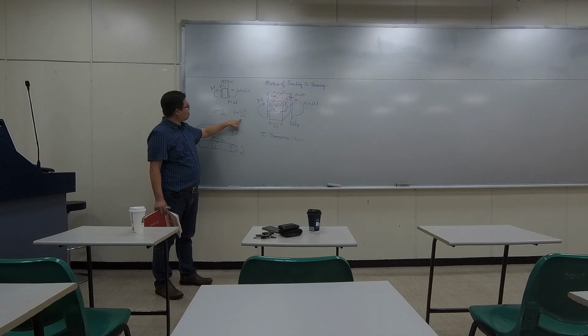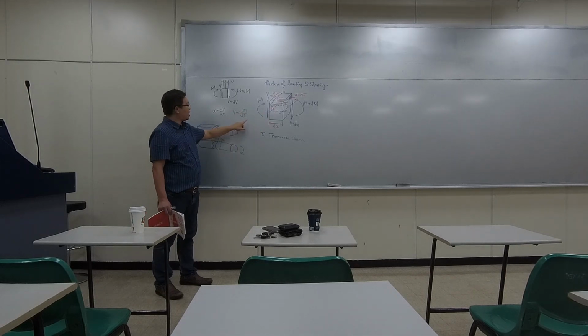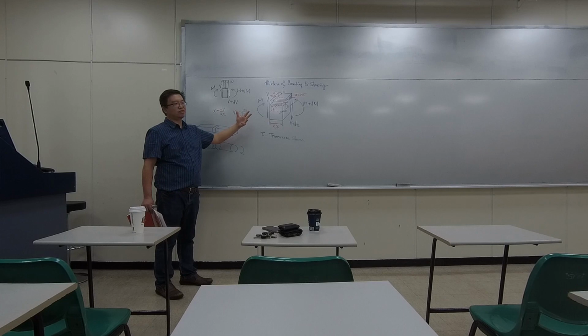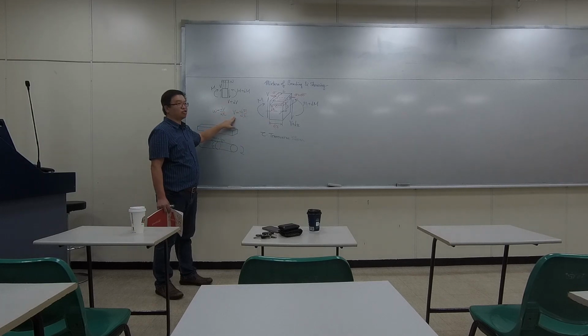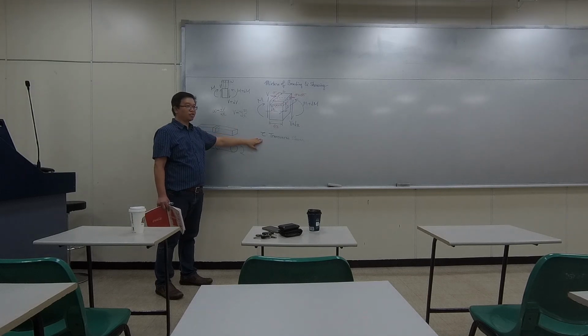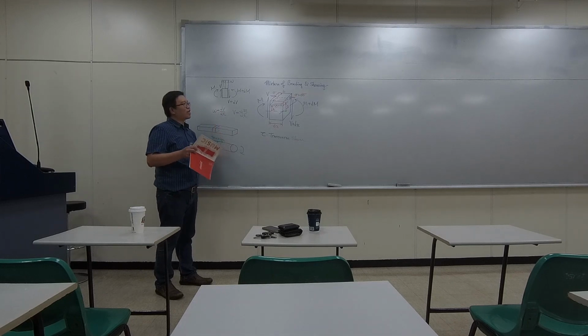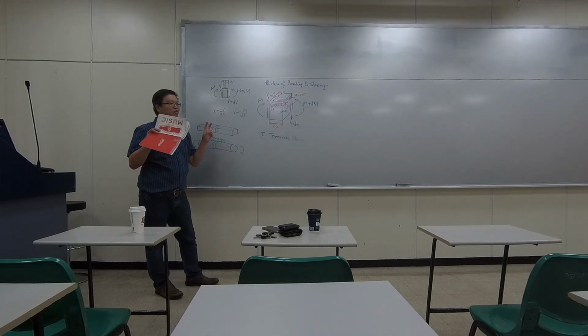If you have constant moment all the way, then every time you move your X, your moment doesn't change. In that case, there's no shear. If there's no shear, then you don't have transverse shear. Okay? So this is the case of so-called pure bending.